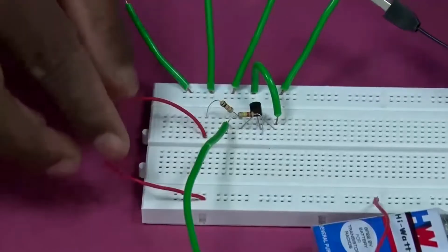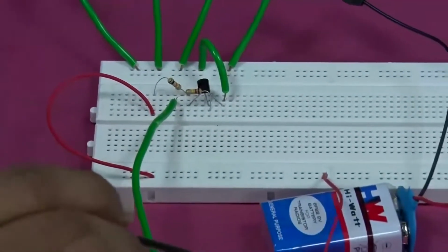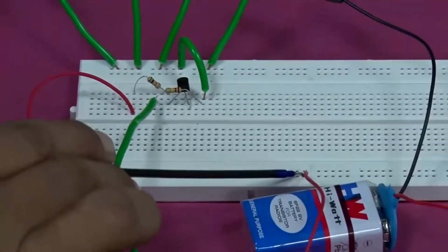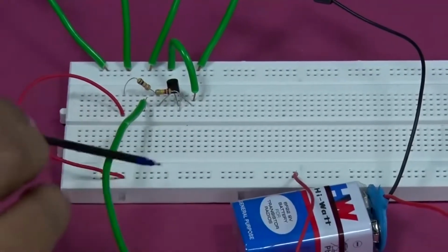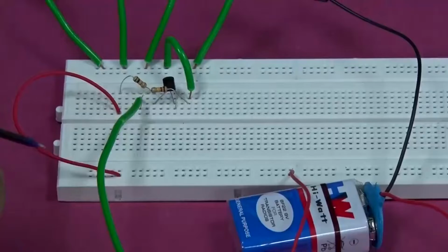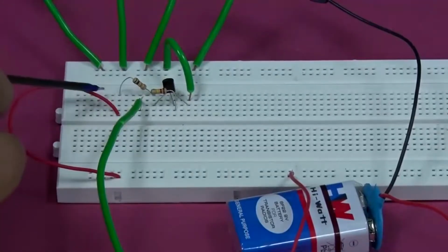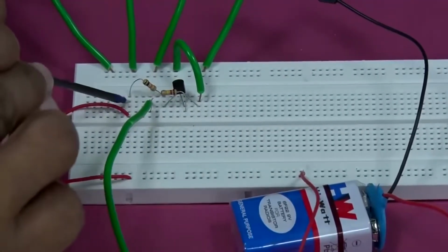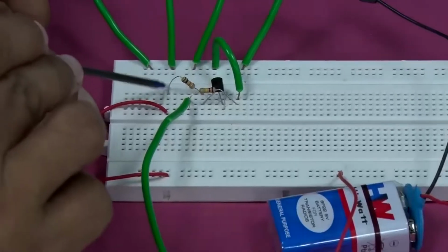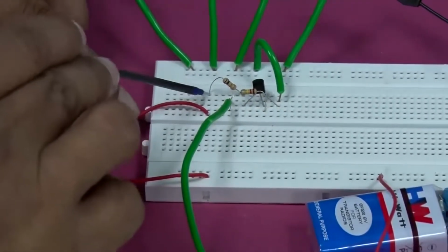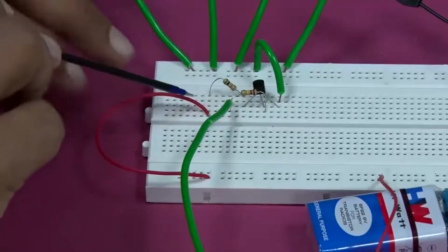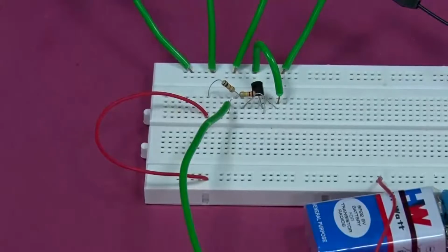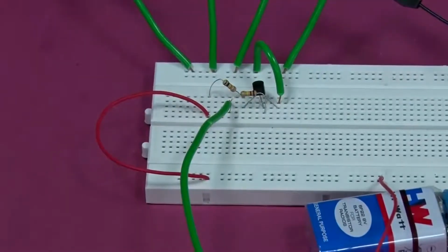Very good. So, you understand the working of the breadboard. The positive of the battery is joined here, but these are all internally connected. So, that 9 volt which is here is also coming here, and from here I am going to this point, and these ones are internally connected. So, this 9 volt has been connected to the other end of the resistance. One end of the resistor is already connected to the collector. That part is done. The negative of the battery is already at ground. So, our output side is also complete.